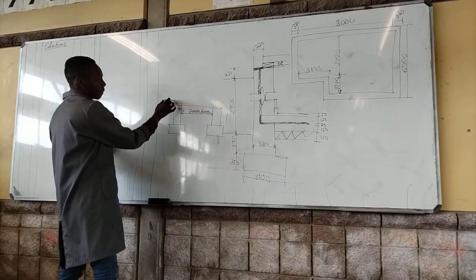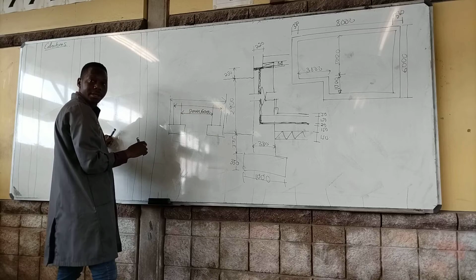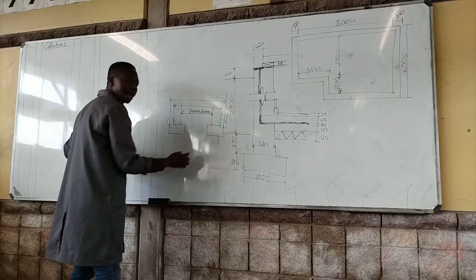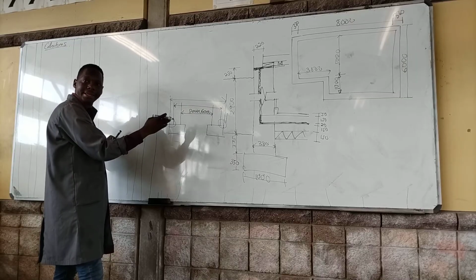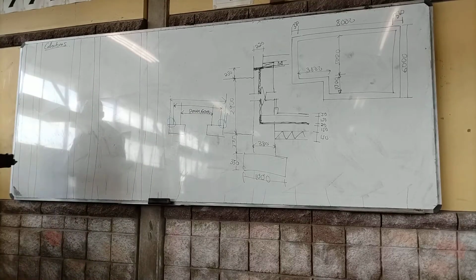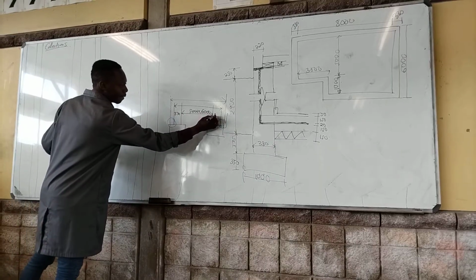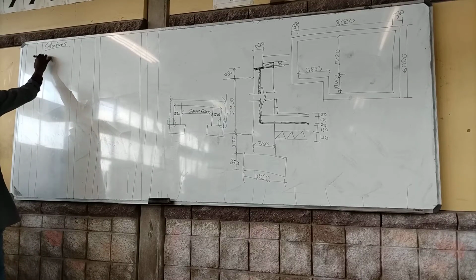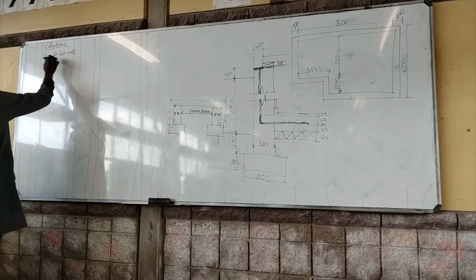I have to identify things here. My basement hole starts from here to there. So what is it that I have to calculate also? The external backfilling, in order for me to calculate the length and the width of the basement hole. Let's start with it. On our connections, we are given the internal dimensions, and the wall here is 330. So let's find the length first, the dimensions of the building, the external walls.